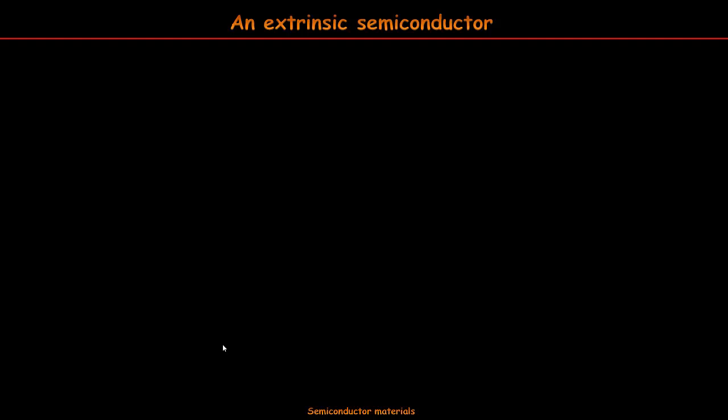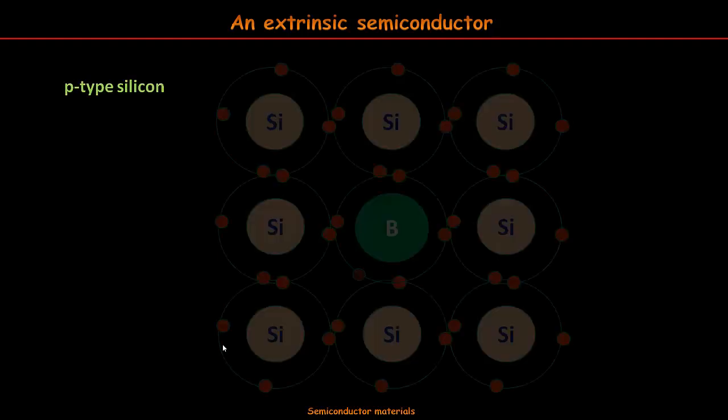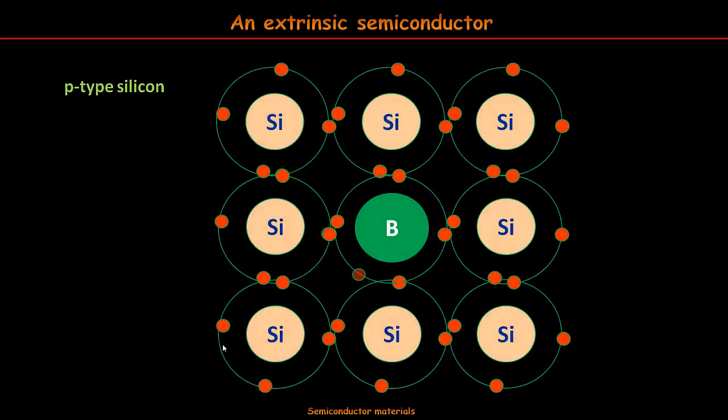In a P-type silicon, the idea is the same, but inserting into its network an element on the left in the periodic chart, for instance, boron. This one has only 3 electrons in its last layer. One of its bonds is electron empty. In fact, it behaves as a hole. A nearby electron might recombine with it, leaving another hole behind. The process of electron-hole recombination can be repeated constantly. Technically speaking, it is the same as if we could say the hole is moving along the material.